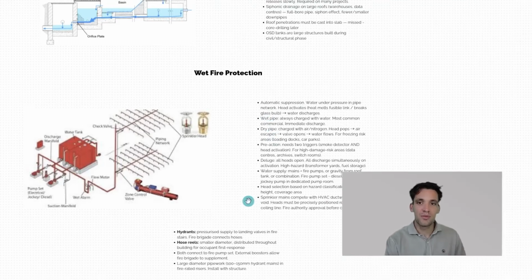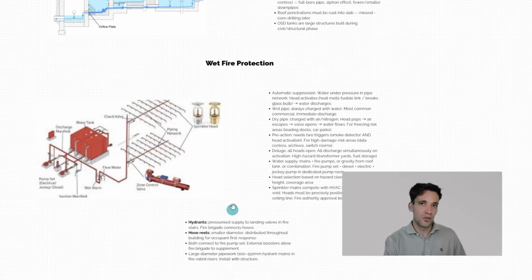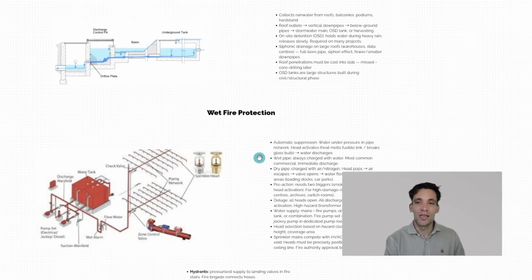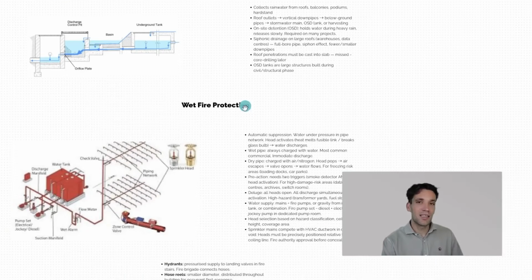And then finally, on larger commercial buildings or industrial facilities, it will typically have some sort of wet fire protection system, which may have its own pump system, or it may have hydrants that the fire department can connect through, and then some pressurized distribution of that water that flows to sprinklers, so when a fire starts, the sprinklers turn on. Now, the dry fire protection system would be covered more under an electrical or a service scope of work, but really for plumbing quantity takeoffs, we're really interested in these 5 different types of services.